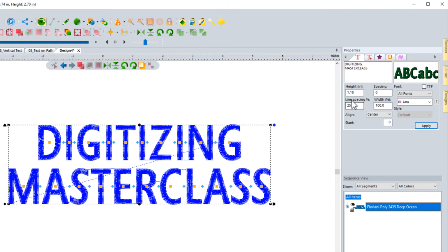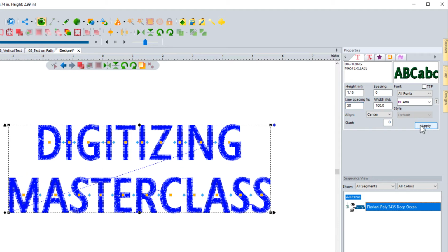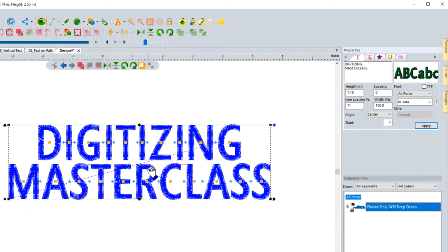And right here for the line spacing, you can see the default is 25. If I wanted more space, I could come in here and type in 50 and hit apply, and it's going to change the amount of space in between. Now I could go all the way down to, let's say, 11, and you can see that it's going to bring it much closer. So if you want to change the distance between rows of lettering, as long as you have it created this way where you have 2 rows inside of this text box, you are able to change that right here in line spacing.